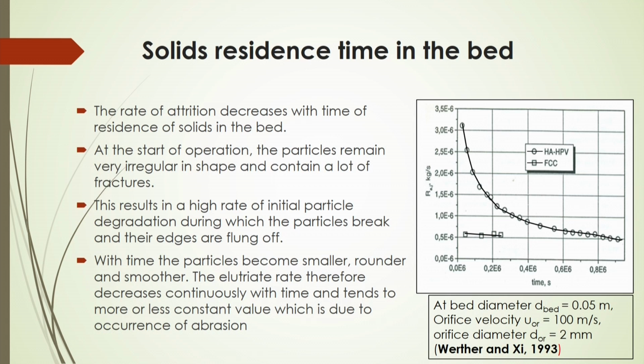And for the high fluidization case, it is seen that the residence time of the fine particles is less, and that is why the attrition rate will be less in the freeboard region, whereas in the distributor region it will be high initially because of that high kinetic energy.